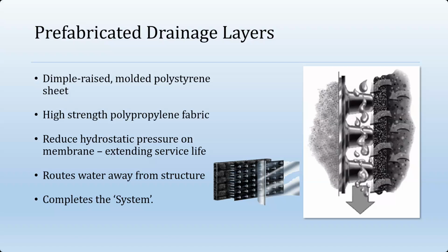And the reason for this is that the drainage mat has an inbuilt fabric, a filter fabric, to prevent fines from the soil from getting into and clogging the drainage core. Secondarily is if we place the drainage mat behind the insulation, how much water is that drainage mat really going to, quote, see? It's not going to see a whole lot.